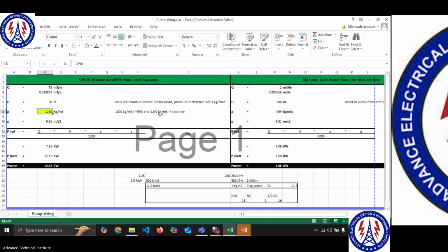The shaft is this 65%, then P motor. How did we calculate the P motor? For P motor we take about 90% efficiency. Whatever you give in the motor, 90% gets converted to shaft power. So it is divided by 0.9, because I need more power.